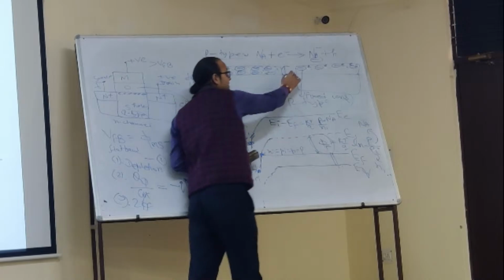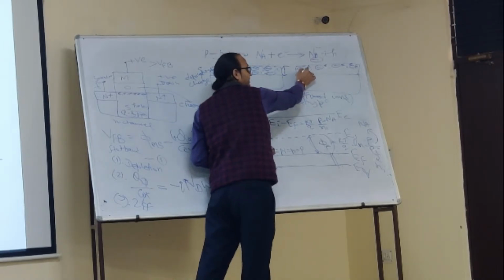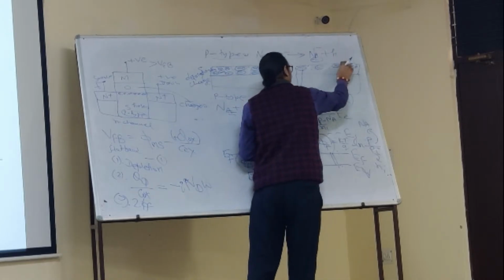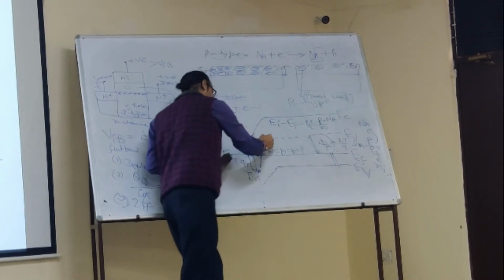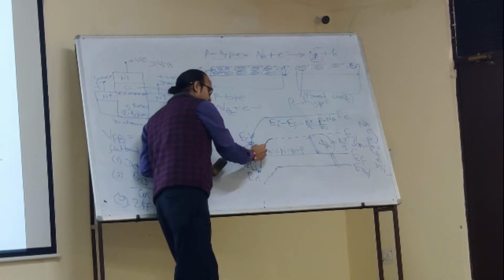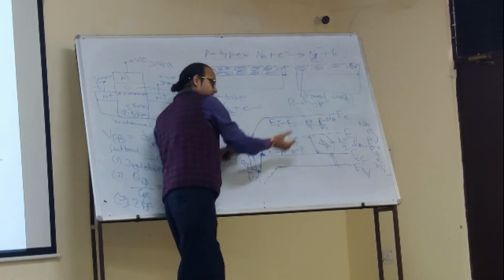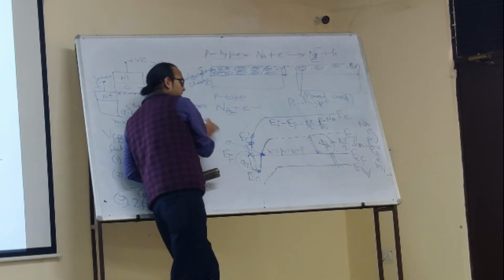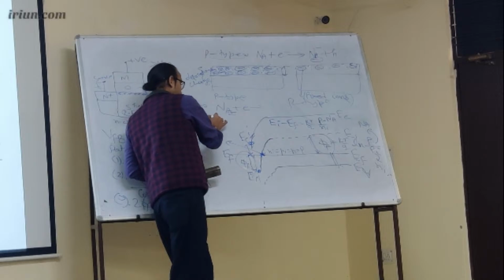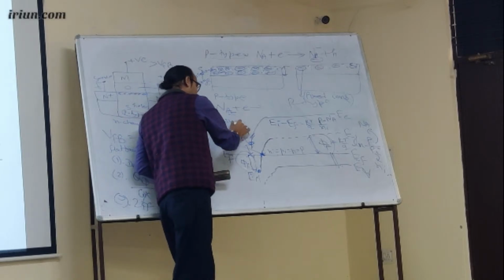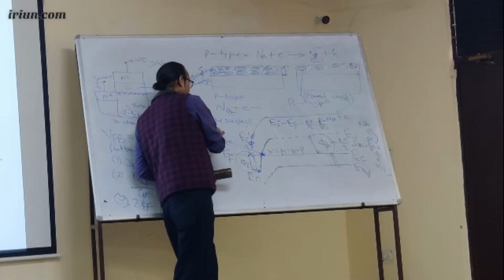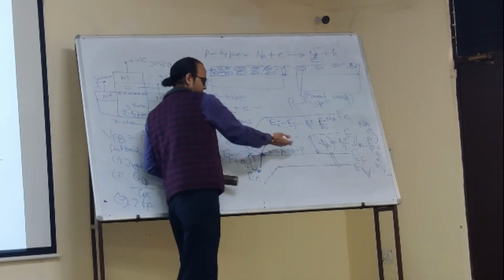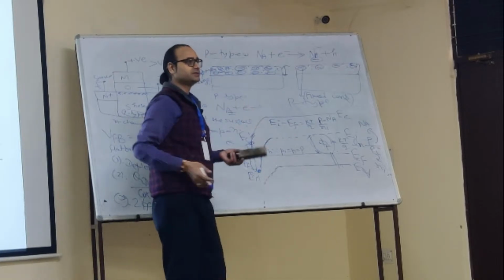Electrons are coming at the surface and recombining with those holes and generating depletion charges. That surface is depleted. This process continues here. At this point, when this much gate voltage is applied, what will happen? Please note this point: at the surface we now have n equal to p, and that should be almost equal.